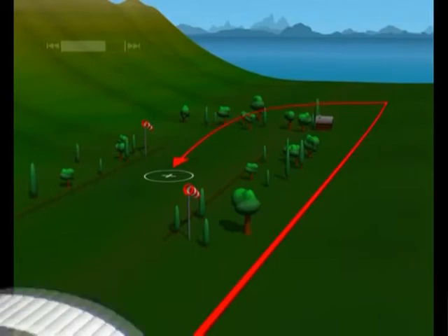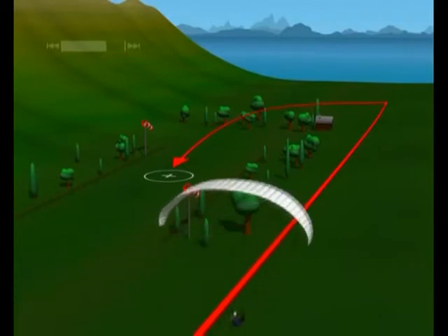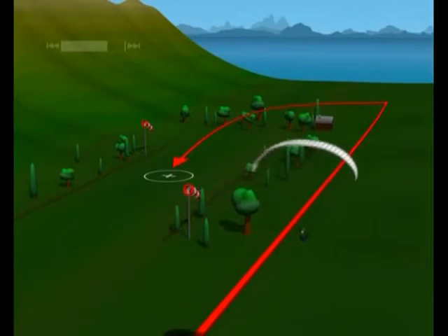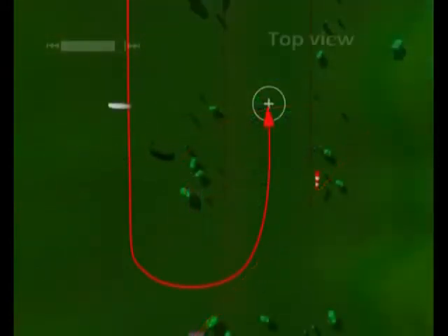The U, or standard aircraft approach, has 2 phases. This approach is also called constant aspect approach. The first phase: without taking his eyes off the target, the pilot approaches the landing field along one of its sides. Though unusual, the pilot will be flying downwind during this phase. He needs to take this into account when assessing his airspeed.